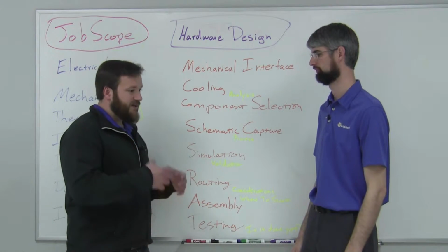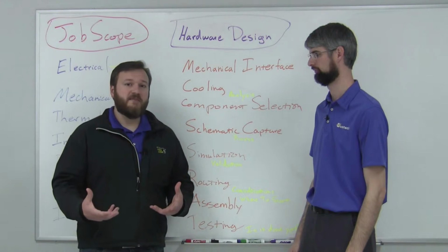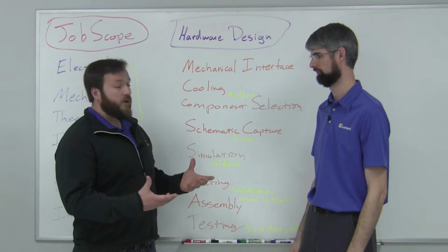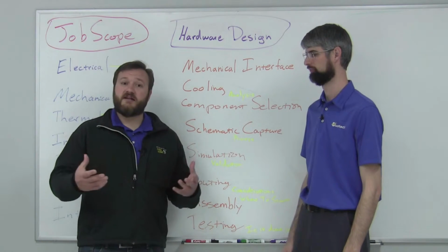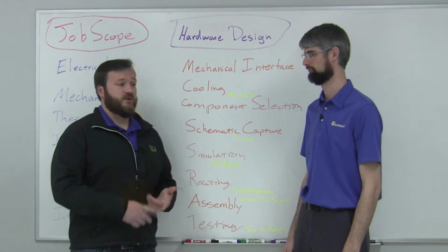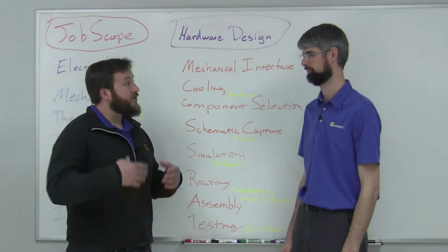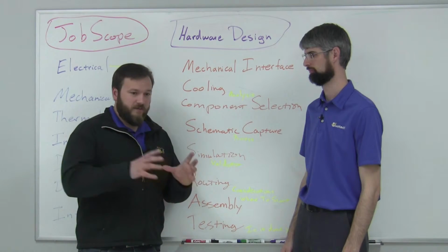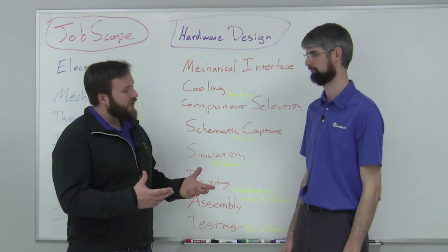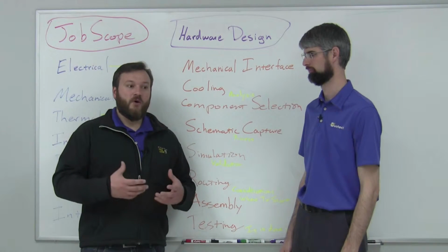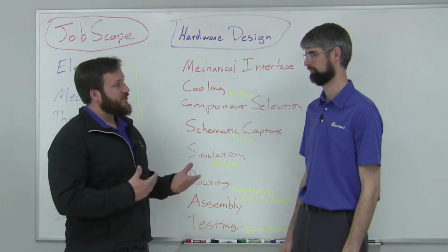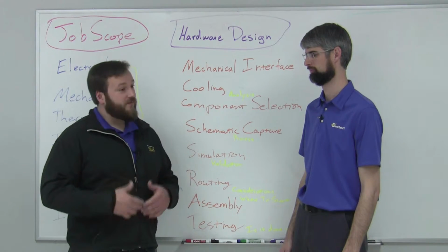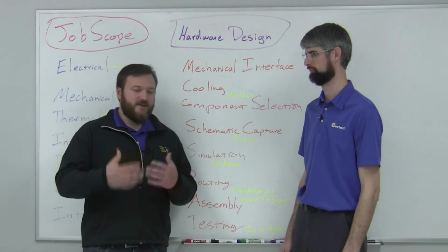And when it comes to actually assembling and producing that board, we may be dealing with a very basic material like FR4, or we may have something more exotic, something that may require a Rogers 3000 or 4000, or polyimide, or a more advanced material. And when it comes to putting those devices on physical boards, whether flex circuits or other things, we need to be concerned with how we assemble this. Can I assemble it through traditional means? Am I dealing with pressed-in connectors? Am I dealing with reflow or other assembly issues that need to be thought about down the line?